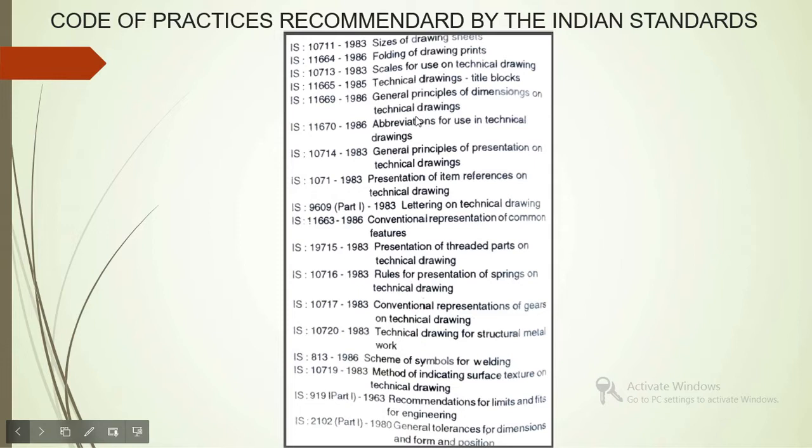Scales for use in technical drawing. For example, 1:1, 2:1, 5:1 are standard scale sizes. That standard is available in Indian standard 7713. The standards about the title block: we have some information like material, scale, and who drew the drawing, and what type of projection.